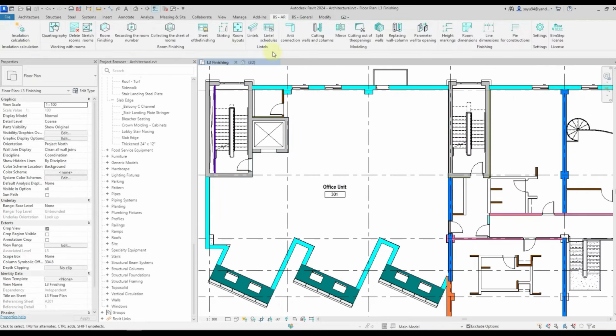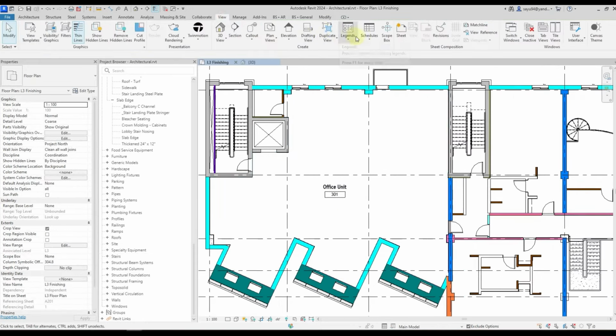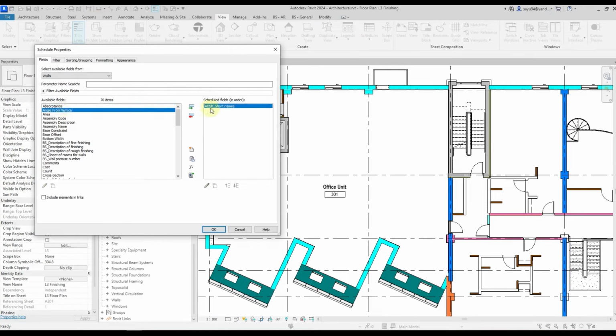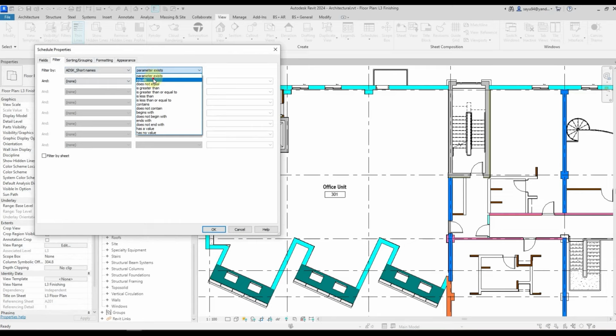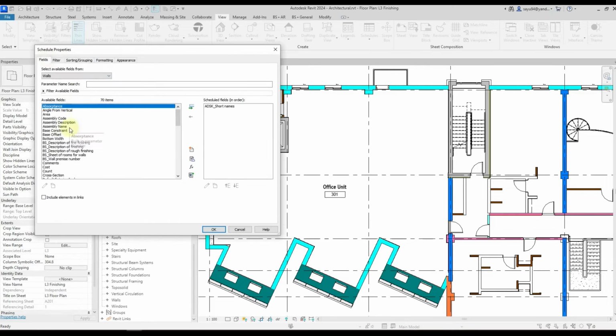Next, you can, for example, do the schedule on the walls. Put the parameter in here, and by that parameter filter only finishing walls. And then further, for example, add our room sheet parameter, and, for example, the area. Also add a wall type parameter and get the schedule.